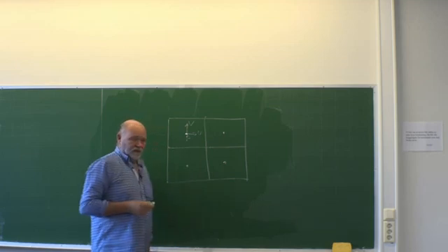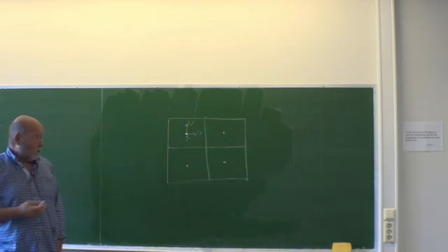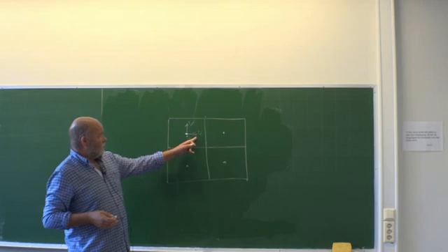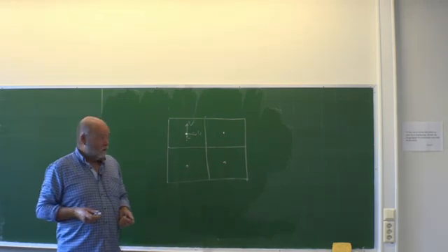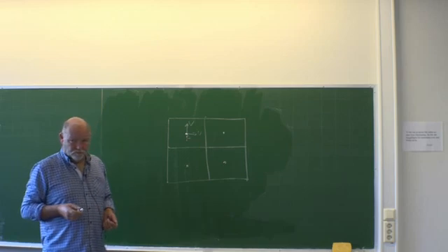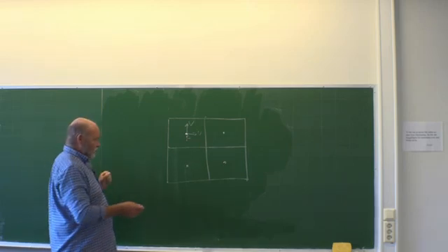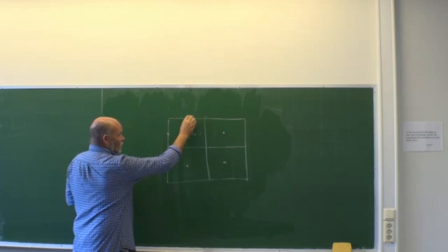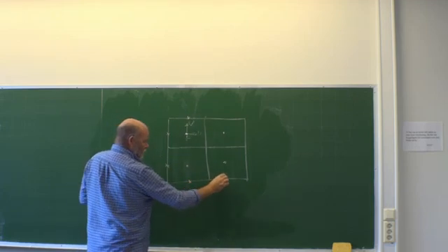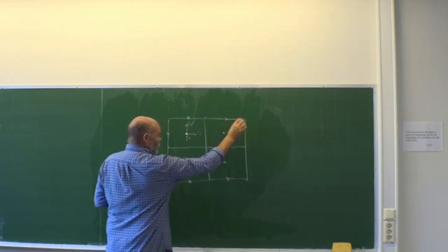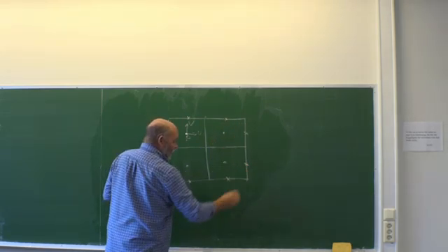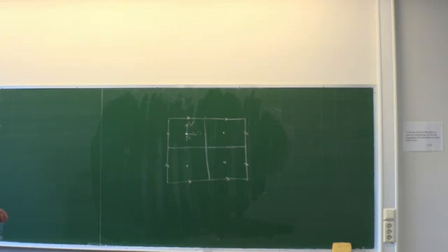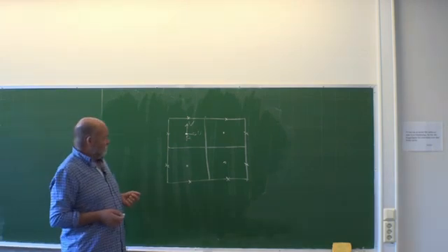So I should then have 4 unknowns for pressure, for U velocity, and for V velocity, and nothing more. But it needs boundary conditions. So it also invents a point here, here, and here, and down here, and so on, all around the boundaries. These are for the boundary values. So yes, I have this one in addition. Fair enough. Shouldn't be that many, should it?